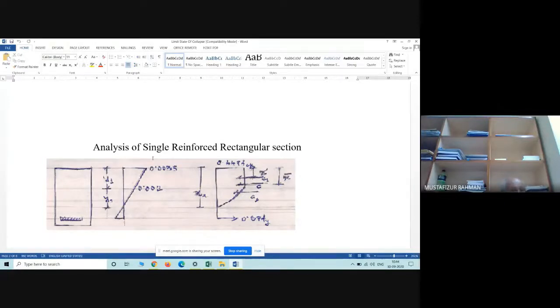That means in the upper part, we do not require any reinforcement, that means we do not require to utilize steel. But the bottom part has a tendency of expansion. The concrete is weak in tension, and also we have made an assumption: tension in concrete is neglected. So if that is the situation, then who will resist the tension?